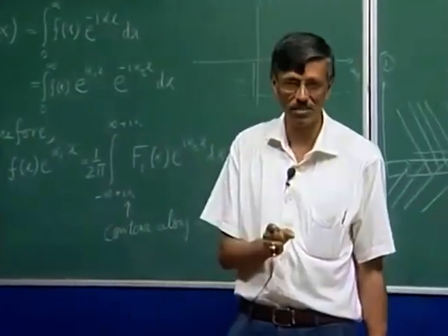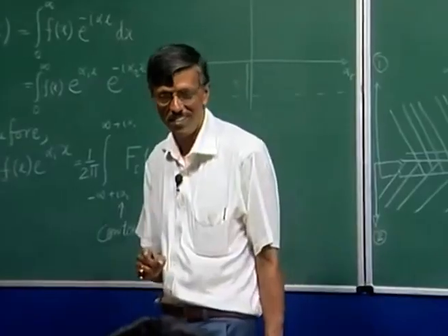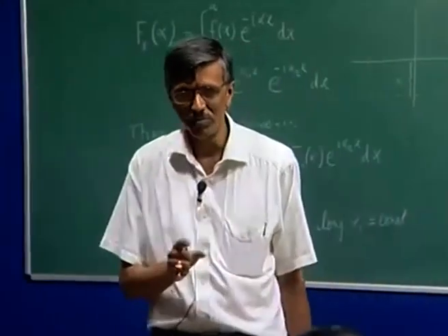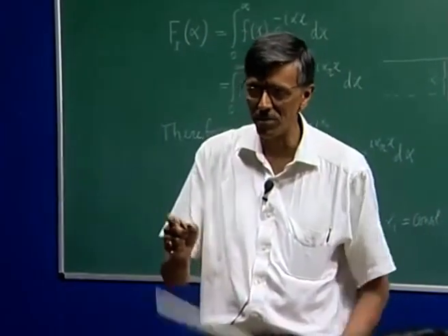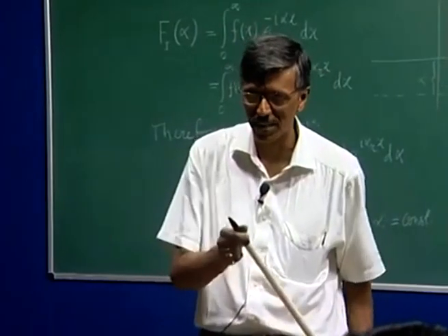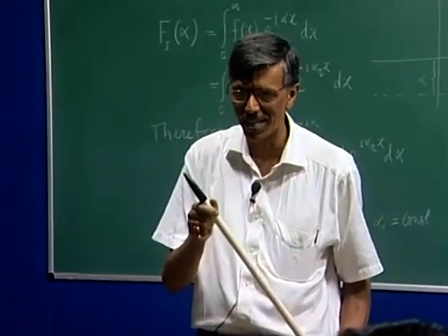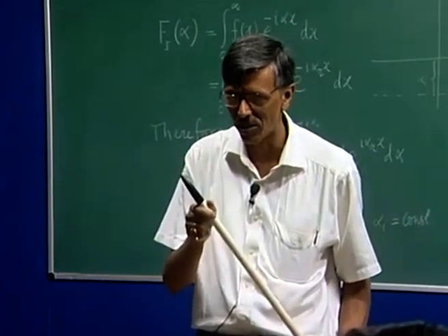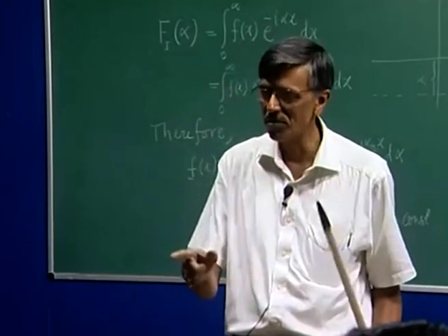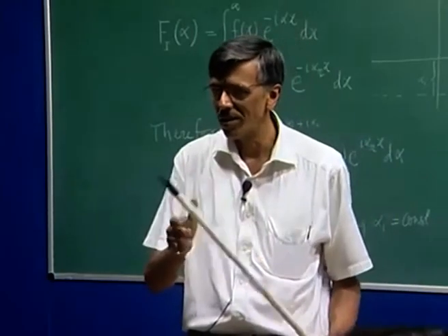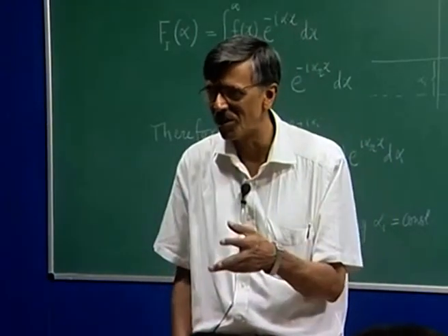That is the connection between your receptivity and eigenvalue analysis. Now, you can see that when we assume that we are dividing by 0, it means we are trying to excite the system at those eigenvalues. And if I also have a numerator which is not exactly equal to 0, or even if it is vanishingly small, then we have the indeterminate form 0 by 0.